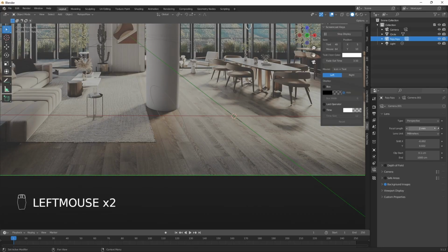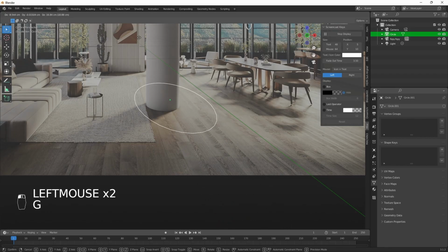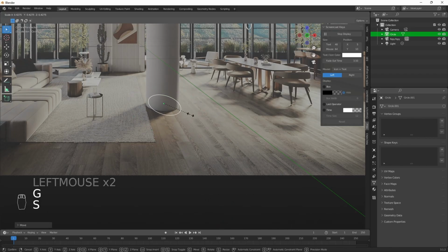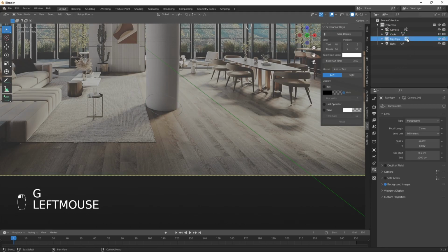So I'm going to increase this to some arbitrary value, let's say 7. And now I have to retry what I already did, which is matching my circle against the pillar base. It looks better, but still not good enough, so we'll need to check some other values. Remember that if you prefer to use field of view instead of focal length, just change the unit. By the way, our field of view has been recalculated and it's lower now, 137 degrees instead of 167.